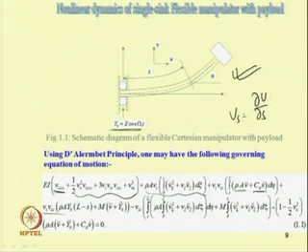Similarly, these are the nonlinear forces acting on the system, and this ρA y_b (L minus s) into V double dot represents the base excitation. So, y_b double dot is the acceleration of the system, y_b is the displacement of the base, and as it is moving in this guide, one can have that inertia force. Similarly, these are the other terms present in the system. So, these terms are nonlinear terms.